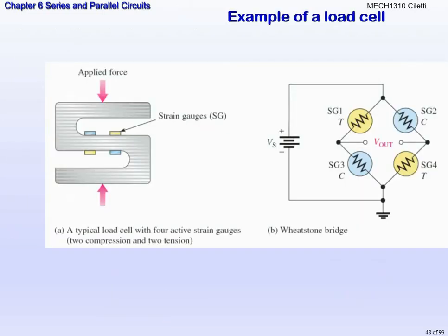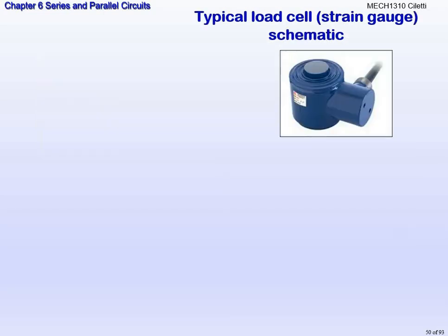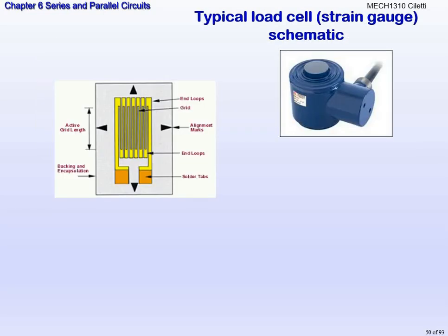Alright, so these you don't have to write down. This is just other examples of where we use a Wheatstone bridge. So we've talked about a load cell, using stress and strain gauges on a scale. So when you get on, you're changing the value yourself. Alright, and how did those work? Well, you standing on it puts strain on the resistance. So as you step with your force down on that resistance, it's changing and making that value vary and then creating that output voltage, which translates into your weight.